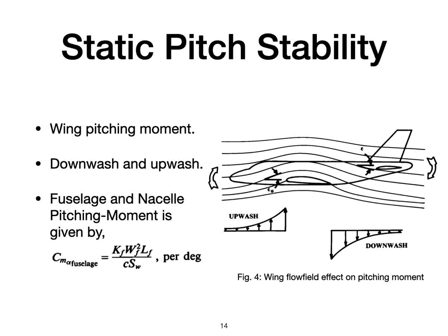Downwash and upwash. Ahead of the wing, the air in subsonic flight is pulled upwards by the pressures about the wing. This upwash pushes upwards on the fuselage forebody and also turns the flow prior to reaching a propeller or inlet location ahead of the wing.